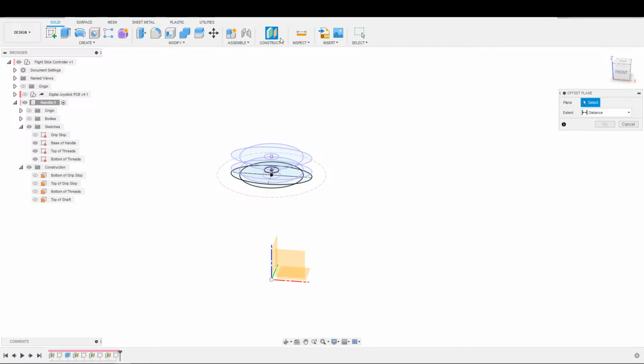So let's see, where do I want my next arc point to be, keeping in mind that loft will do its thing. Top of shaft, let's say. So we need to go about 100mm, it looks like to me. Rough numbers, 100mm. 100mm should give us plenty of breathing room on there.